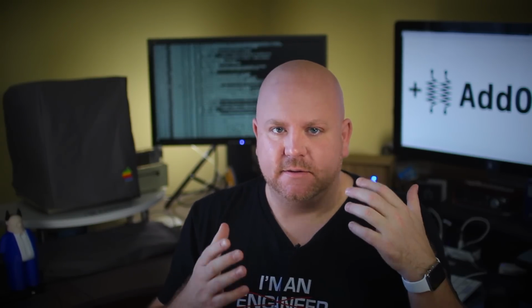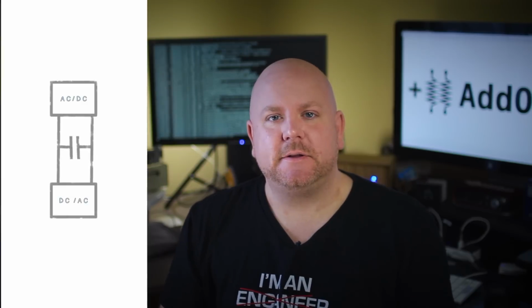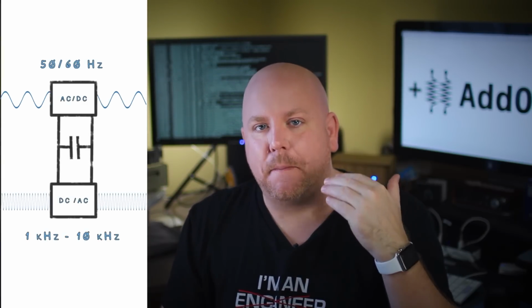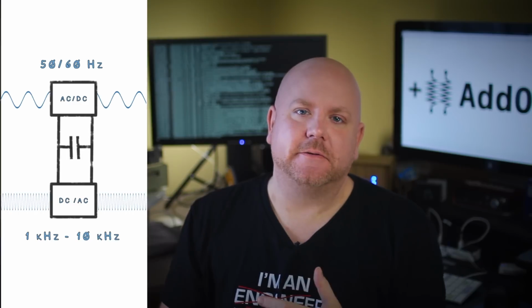And so for example, on a refrigerator, maybe the compressor doesn't run at full power as the target temperature is reached. And so what's really cool about these VFDs, the variable frequency drives, they typically take an AC signal in, convert it into DC, and then convert it back to AC at a different frequency.